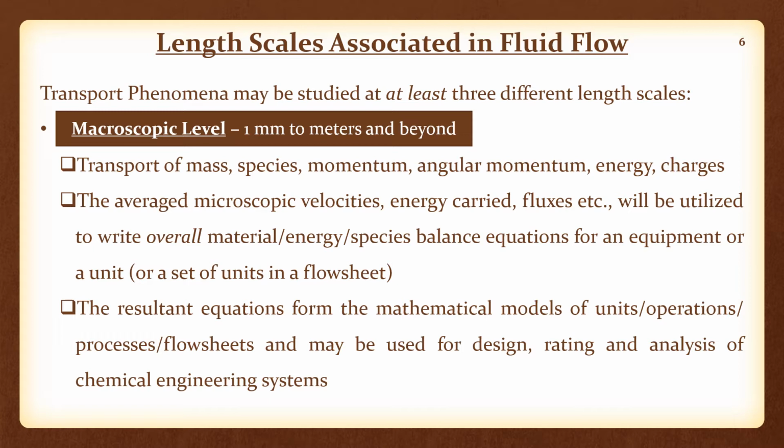So you are not interested in the velocity variations and all. You are quite content with using an average velocity or average flow rate of the liquid phase and the average flow rate of a gas phase, and that is good enough to do the design of that particular equilibrium stage, and that of how many such equilibrium stages would be needed to achieve a desired separation.